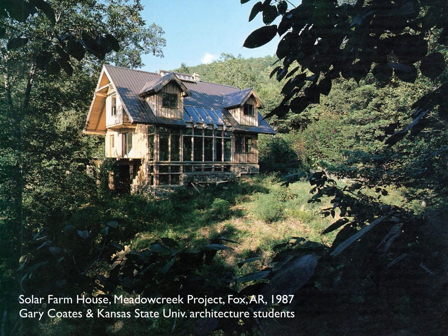This farmhouse building, built in Arkansas from about 1987, was actually built by five Kansas State architecture students, Bachelor of Architecture students, as their thesis project. And again, it uses a series of multiple systems, direct gain, and also a sun space. You can see that big section in the middle is a sun space. The upper dormers would be direct gain.